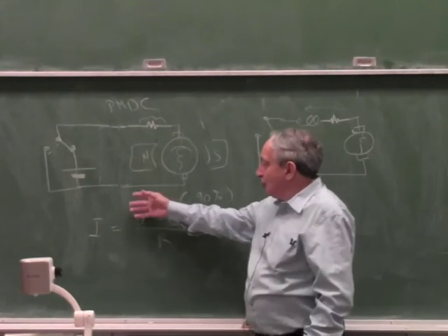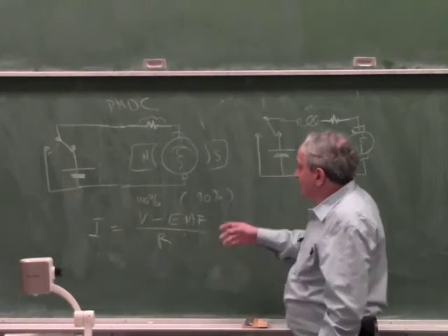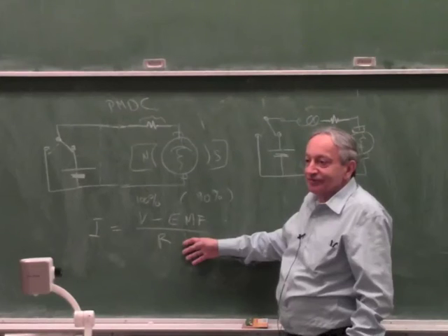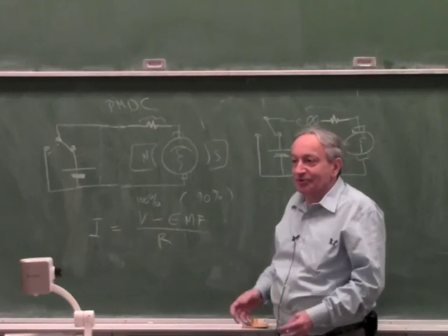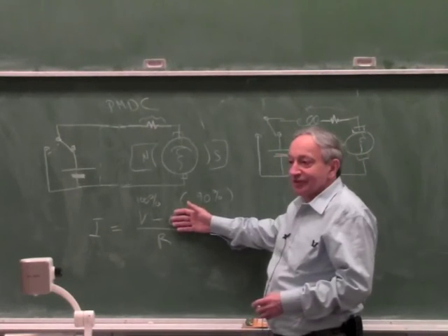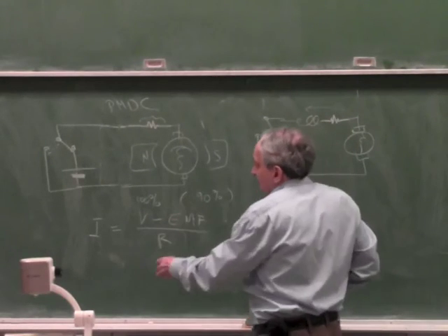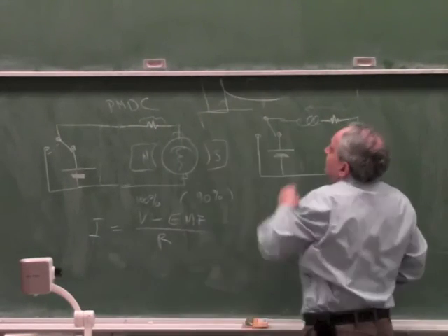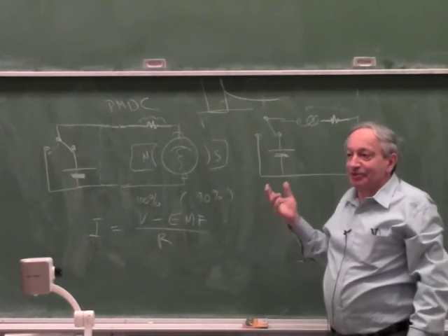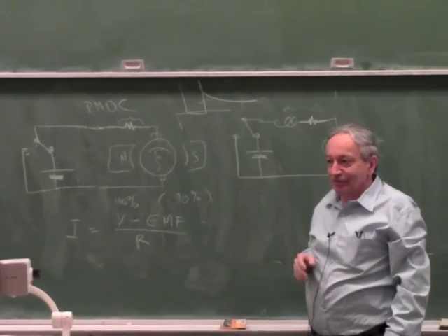But if you short out the motor, the current goes up ninefold. Okay? The same thing happens when you start the motor, because the moment you start the motor, there's no EMF. That's why all these motors, when you draw the starting current versus time, they all start like this. They all start with a huge current spike because there's no EMF, and we talked about this before.